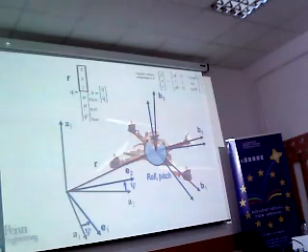So you can see here, as I have told you, that we have the rotation matrix. It will change from the inertial frame to the body fixed frame. p, q, r is the derivative of the angles in the body fixed frame with respect to the inertial frame, through this coefficient matrix. This set of equations tells you everything you need to know about the kinematics of the quadrotor.